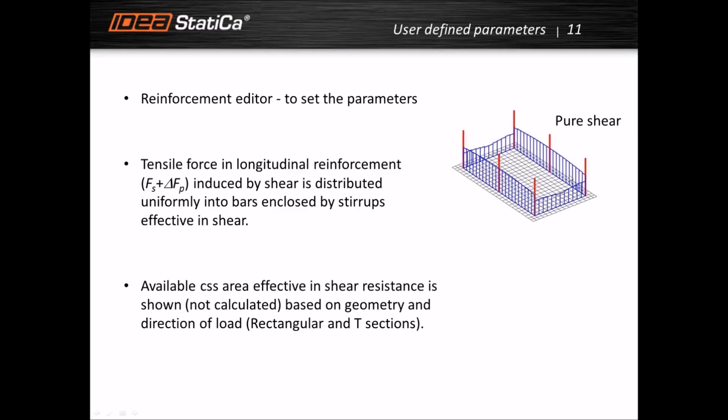The other nice result of this analysis is that if we apply this shear force in the direction which I show now, then not only the stirrups which are parallel to this direction of the shear force, but also the stirrups which are transverse have some stress and resist some stress.